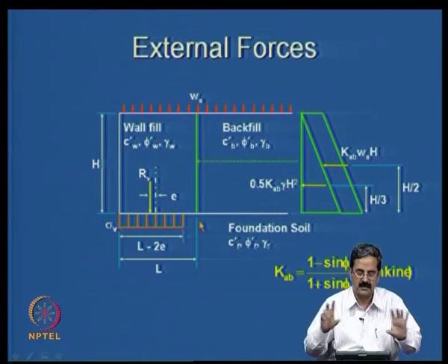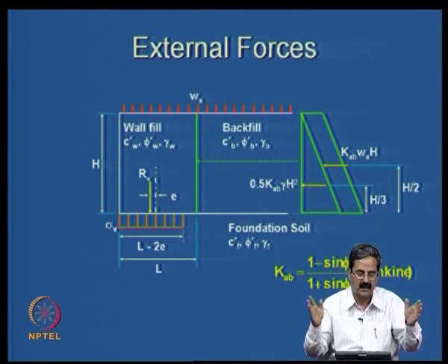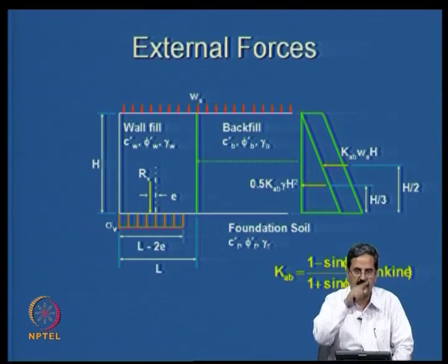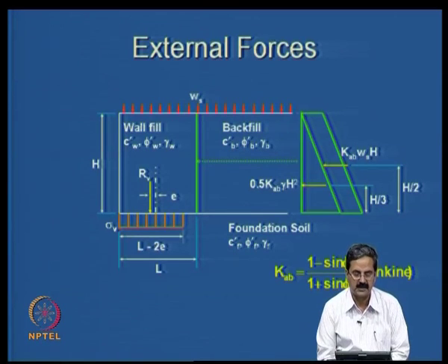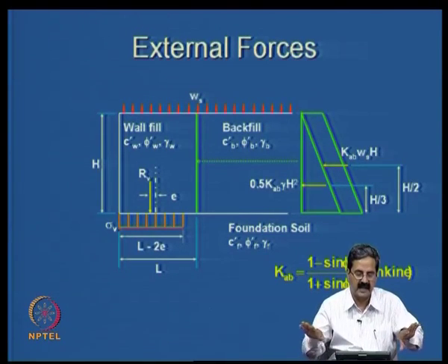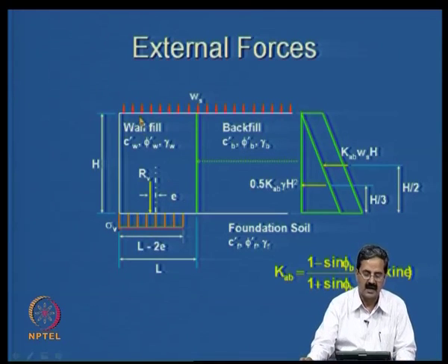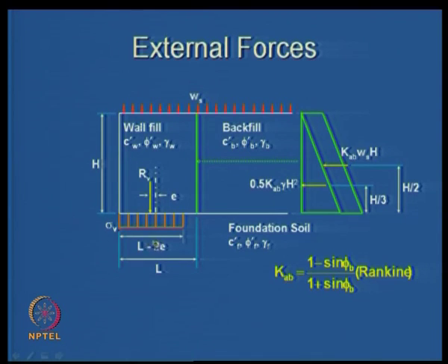In trapezoidal distribution, we assume that you have a maximum value, you have a minimum value, and the distribution varies in the form of a trapezoid. But that is valid in the case of rigid foundations. Reinforced soil being a flexible structure, any pressure gets redistributed, and you will have only a constant value. That is the maximum value sigma V you get, and this is a usual thing. So this is another important thing, called Meyerhof distribution.